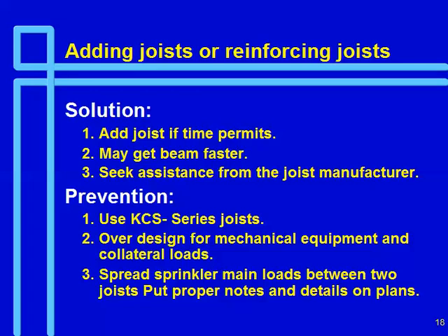You may have to reinforce the joist or joists that are there, and I urge you to seek assistance from the joist manufacturer. They have some nice standard details, and they can give you some help. They're like anybody else, though. If they're really, really busy, they'll kind of blow you off. And they'll say, you know, I can't get to it right away, or it's going to be weeks. They're like you and I. So you may have to do it yourself. And we've mentioned how to prevent the problem.